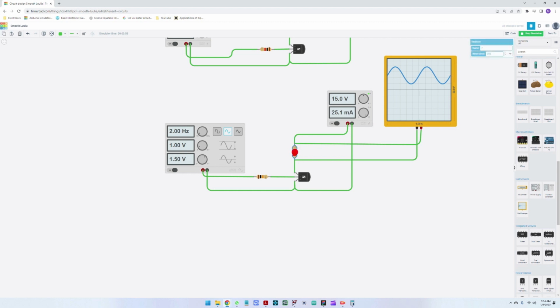If we increase the load a bit so that we can clearly see the signal, you can see that the signal is going from, here are 20 volts, so from top to bottom, and here are 10 volts from one side to another. So our signal has about 5 volts output, and we've inputted about 1 volt.